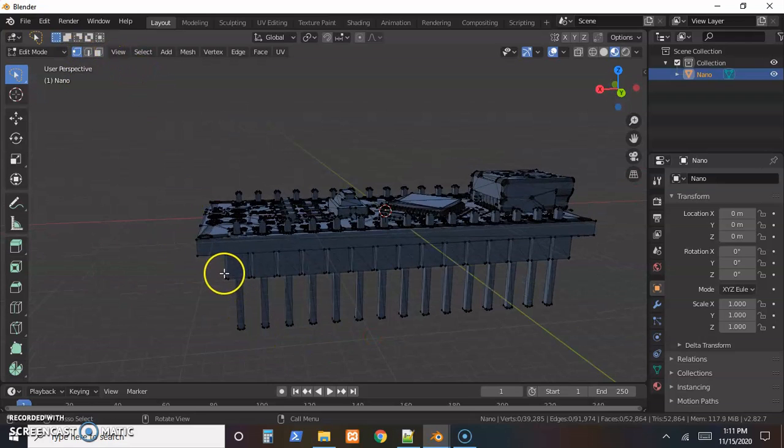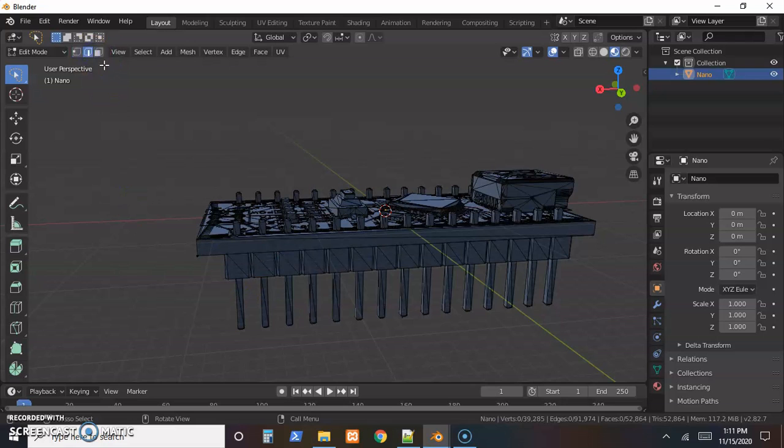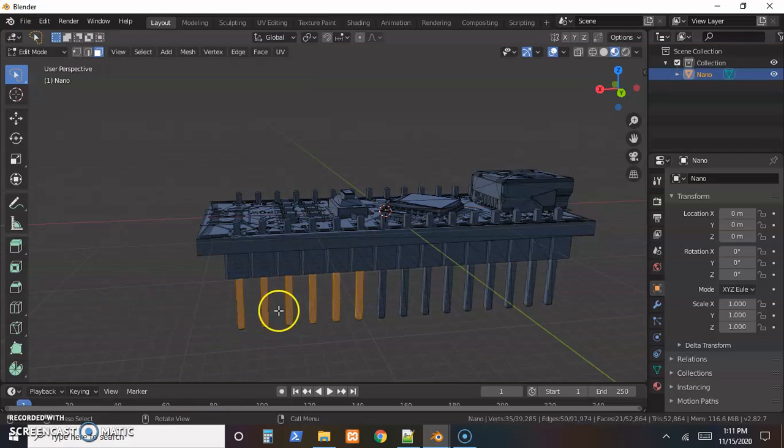So right now it's set to select vertices. With vertex, if we select every vertex that surrounds the face, it'll select that face. Or edges, but since we're recoloring by the face, it's probably easiest to put it on face selection, and then the freeform selection just has to touch it. So we can just drag across, select a bunch of faces, and those are all part of the pin, so those need to be metal.